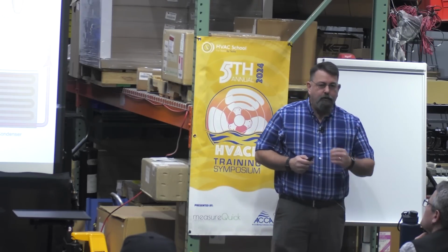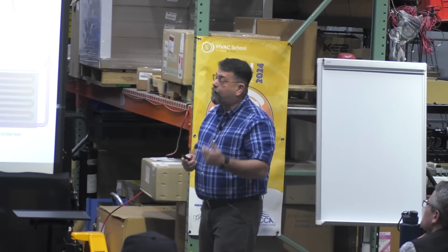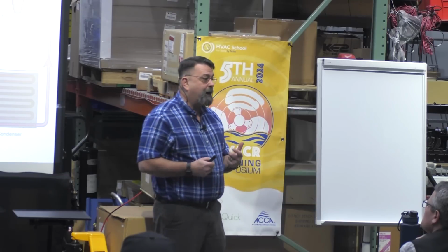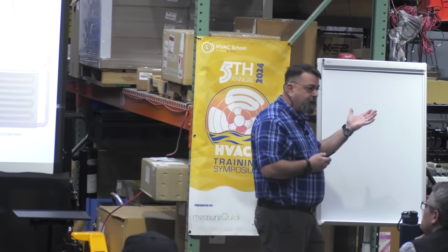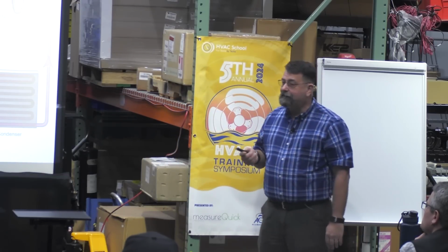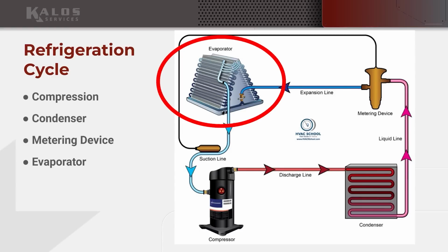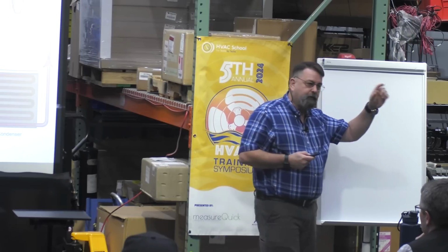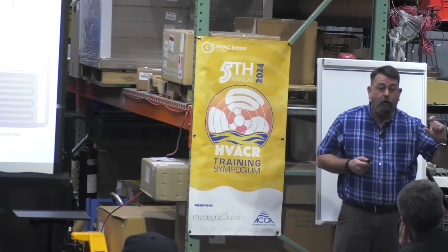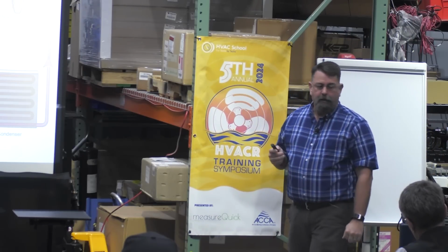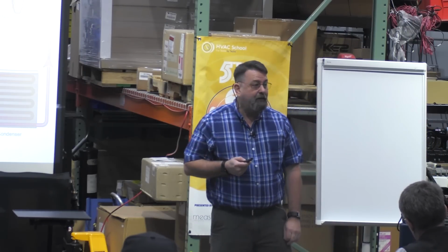When you guys in the air conditioning world talk about TD, you're usually talking about return to supply. When you hear rack guys talking about TD, they're talking about my coil temp to supply. It's a very well-known number, right? It's engineered. It's printed on the tag of the equipment.